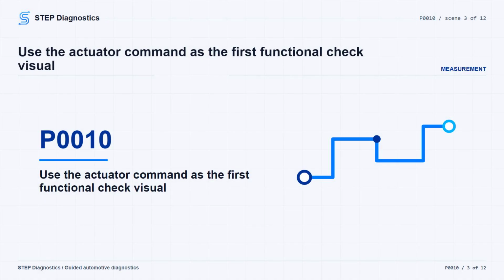With the engine idling, use the scan tool to command the camshaft position actuator from 0 to 10 degrees and back to 0 degrees. While doing that, watch the solenoid valve control circuit test statuses. The low voltage, open circuit, and high voltage test statuses should read OK or not run. If any of those are not in the specified state, move into circuit testing.